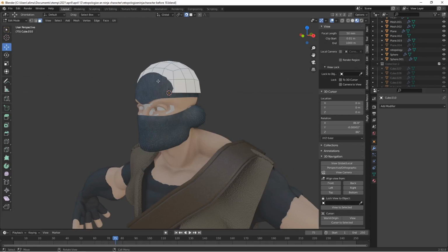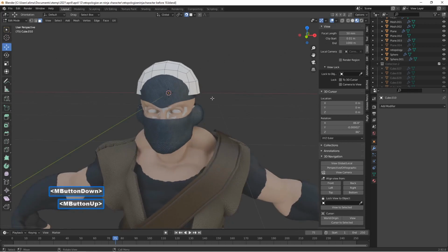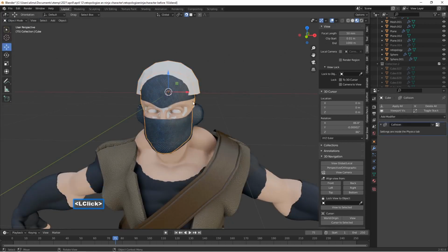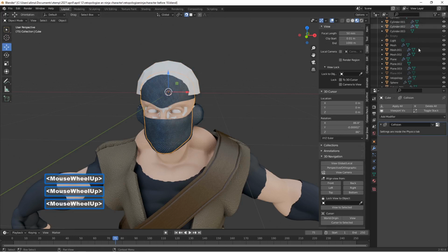Okay, what we're going to want to do is to apply a shrink wrap modifier here. We're also going to want to cut this in half, and then the plan is to join this to the retopology mesh. So we're going to quickly go through that. So we're going to go to the upper left, go to object mode. We're going to select our main head mesh. This is the outliner here.